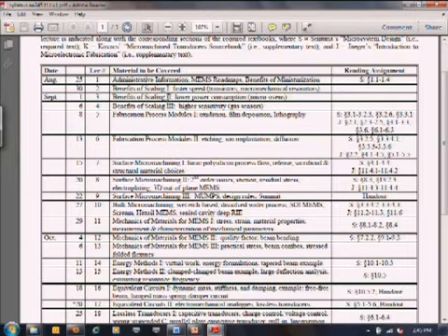The reason why MEMS in many ways is more difficult than CMOS is because you have to deal with stress and strain. Things can bend out of the plane when you don't expect them to, and you have to learn to control that. In the end, CMOS, I think, is a lot more difficult than MEMS if you know how to control stress. MEMS, usually you have just 3 or 4 masks, 5 mask processes. CMOS, how many masks? Device guys. You can have up to 40, right? A lot of masks in CMOS now. So CMOS is a much more difficult technology to do than MEMS.